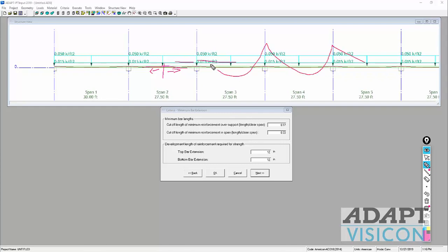So if I have a moment diagram that looks like this, then we determine, okay, where's our cutoff inflection points? There's 0 moment here and here. The program might say, okay, take half of the demand. If this AS, I'll call it ASM, AS max. If I go down and cut that in half, maybe this location here, this is called, let's say, AS2.